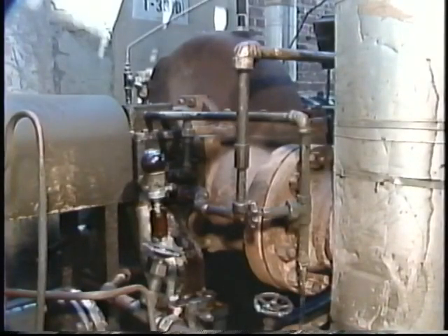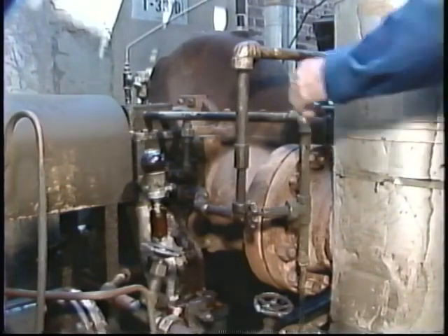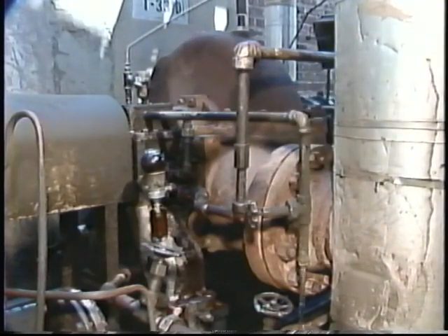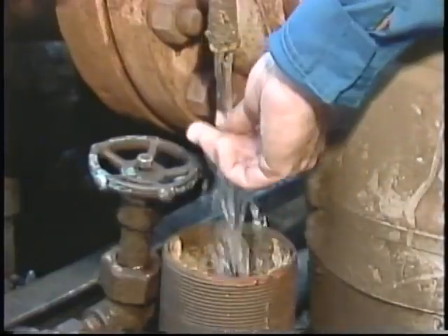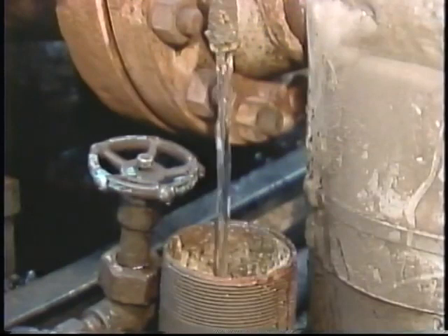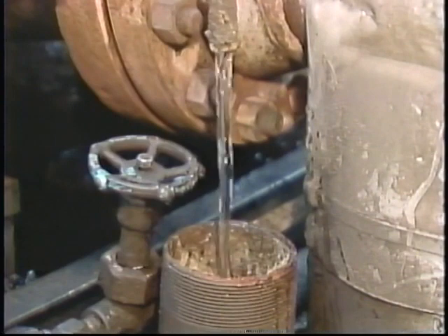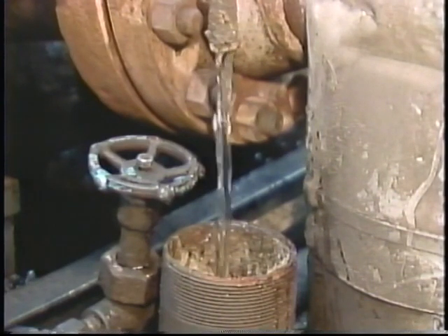Likewise, the bearings could get too hot if the cooling water system isn't working the way it's supposed to. For this reason, the cooling water flow must also be checked regularly. On this turbine, the operator can feel the cool water flowing through the pipes into the turbine. If the lines feel cool, that's usually a good indication that the system is functioning properly. He can also observe and feel the cooling water being discharged after it has passed through the turbine. A steady discharge of water generally means that the system is okay.